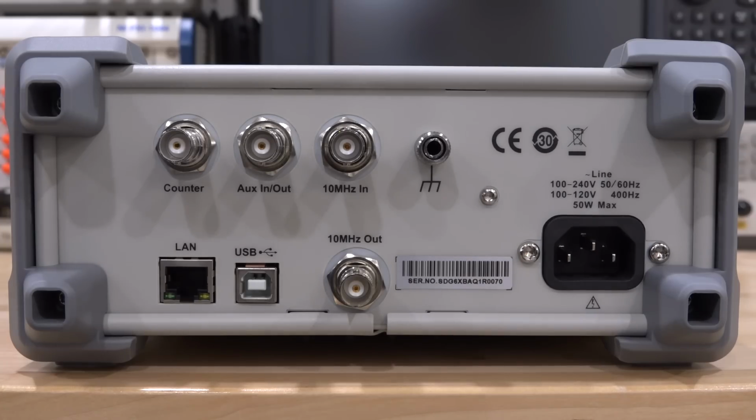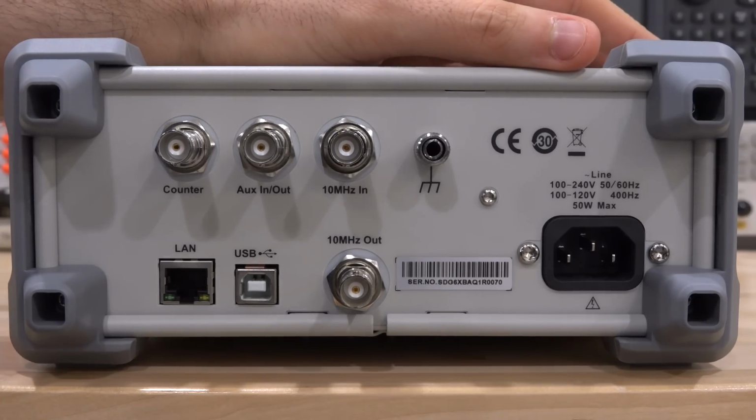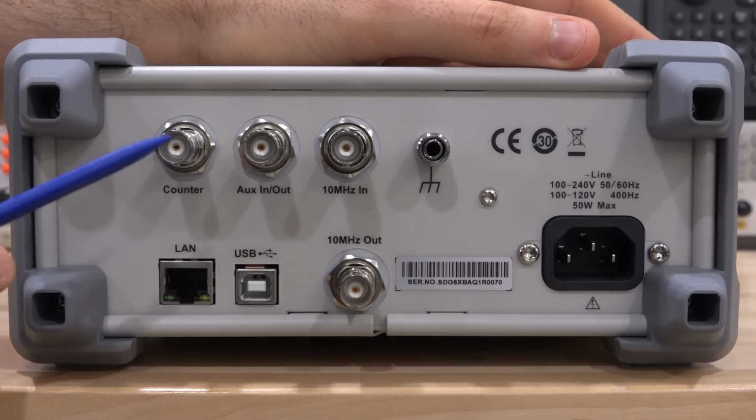It's actually quite useful in the lab to have this, so I like the design from that point of view. And here's the back of the unit, which has a nice set of connectivity. LAN and USB is standard. A lot of these units from these vendors often have this as standard, which is nice. You can connect to the unit over several different types of VISA interfaces. We have a frequency counter, which relies on the internal 10 megahertz reference in order to have an 8-bit frequency counter, hardware counter, to tell you what kind of signal is coming in, which is very useful.